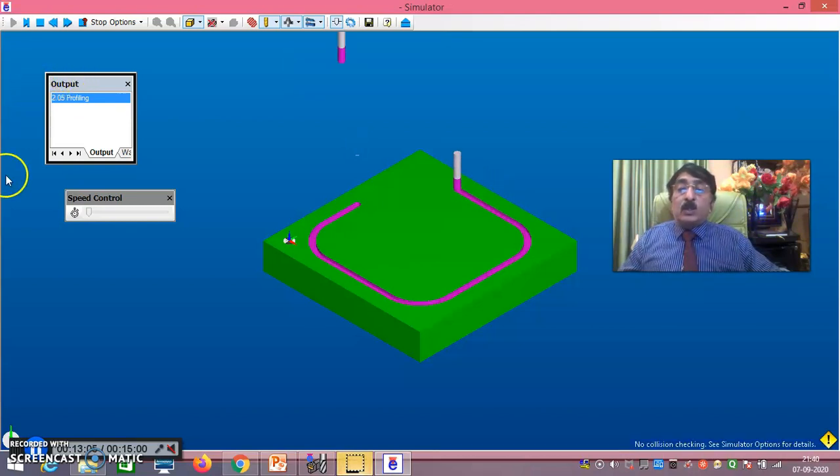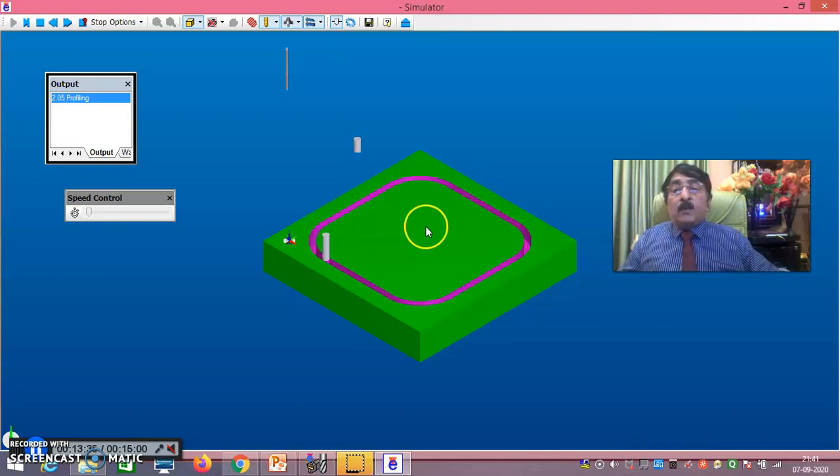This is -2 mm. Then now it is going -4. You can slightly increase the speed also by changing this. Then -6, -8 and -10. In that way, you will have a slot created. That is going along this is called profiling. And cutting the entire material, we call it pocketing, which we'll do in the next sessions. Going along the profile is called profiling.